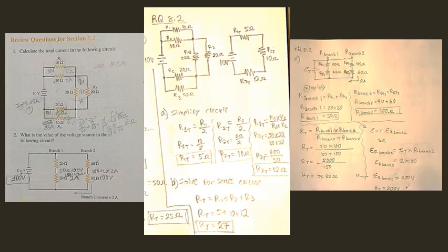That's again at branch 1, which is 50 ohms. Just a simple addition, since we're dealing with resistors in series. We do the same thing for branch 2. The resistor at branch 2, 1 plus resistor at branch 2, 2 equals 40 ohms plus 60 ohms, or 100 ohms total. So we have our resistances at each branch of 50 ohms and 100 ohms.